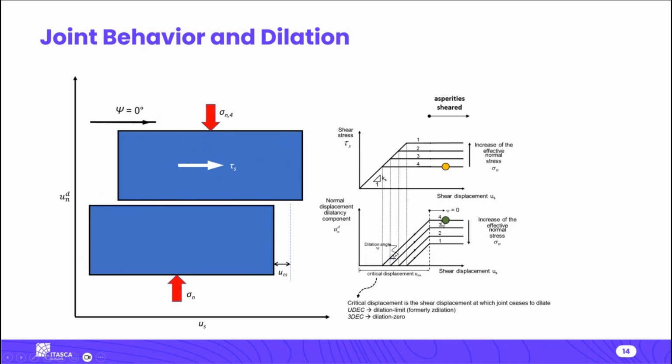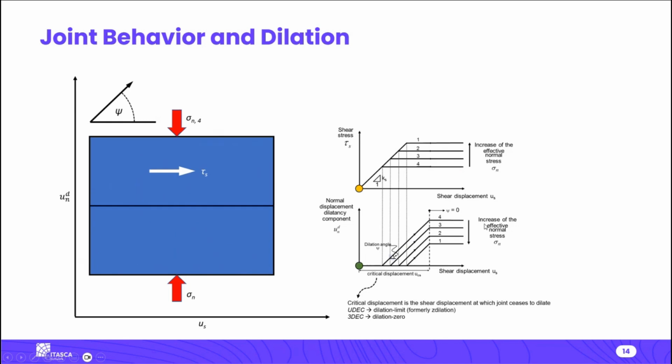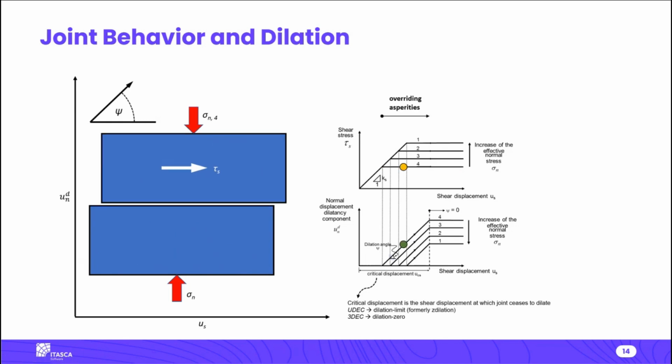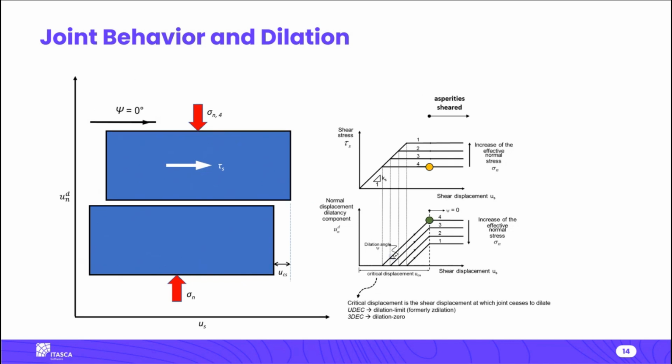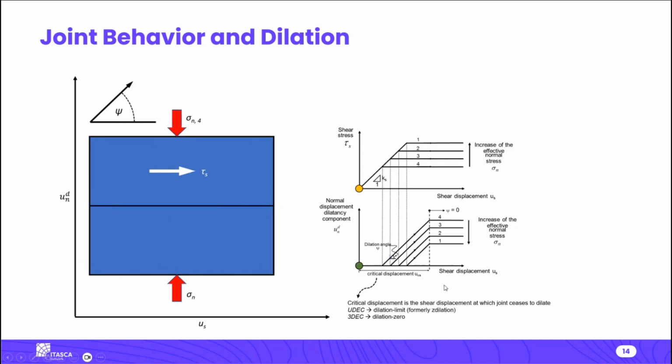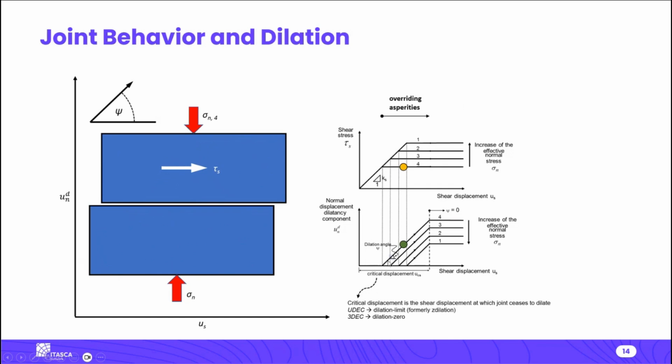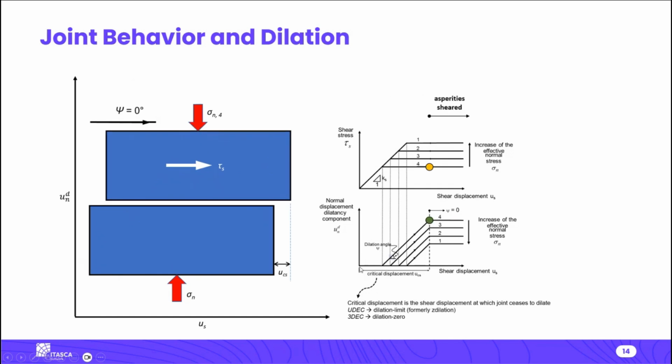And now what happens is if you see a lot of shear, you can imagine you don't want this joint to keep opening forever. That's not realistic. At some point, it will reach a state where it's just sliding along at some constant level of opening. And so what you want to do is give a sort of limit to the amount of dilation that can occur here. So again, it starts out elastically. There's no dilation.